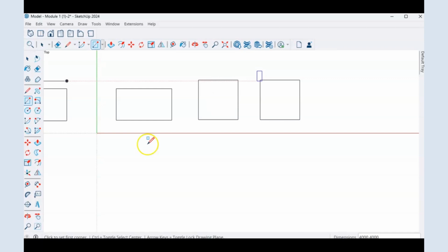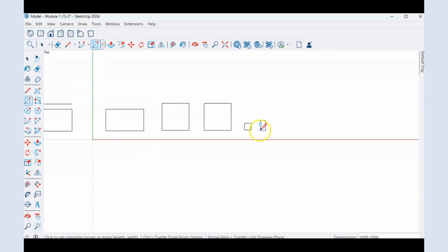We can correct a rectangle size like that. With this next example, let's say I bring a rectangle over and I do 1,000, 10,000, and I realize I've got that around the wrong way. Before I've clicked anything else, I can correct that by putting in the correct dimension, so 10,000, 1,000, and switch it around the other way.